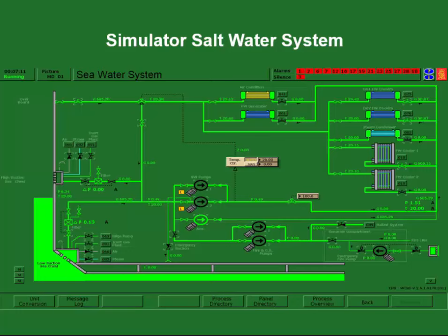If you think that maybe there's a low flow condition through the pump that's caused by pump wear, you would put the redundant unit on and shut down the primary unit and see if that solves the problem. Then you know that you have to do a pump repair. Similarly, on your freshwater to saltwater coolers, if you think that one of the coolers was plugged up, you would switch over to the other cooler and clean it.